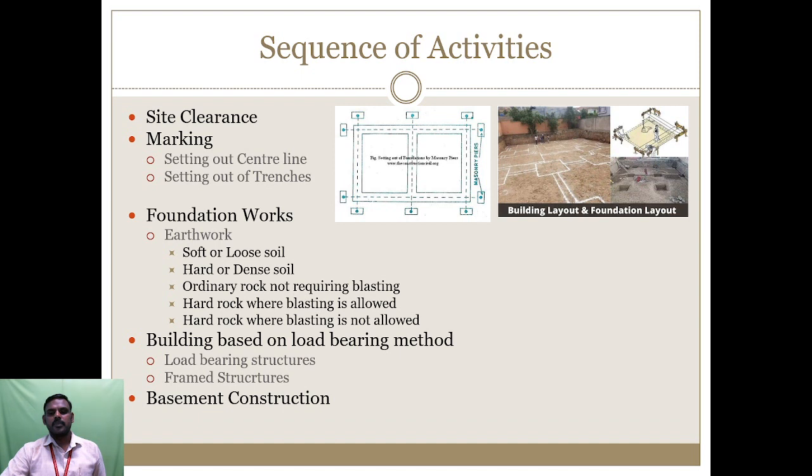That is the belt beam, near to the soil area, the earth beam, next the belt beam. Then the column will be raised up to lintel level. That lintel will connect all the columns, which is known as continuous lintel. If there is a discontinuity in the lintel, it becomes a cut lintel.